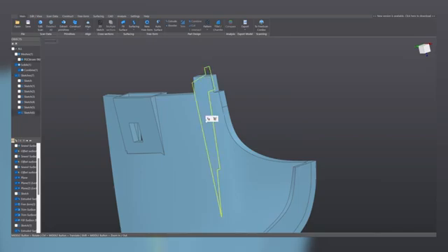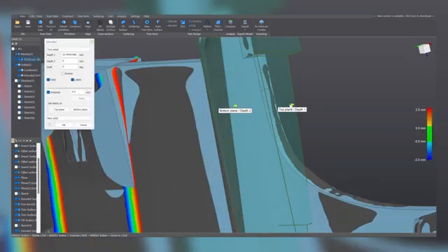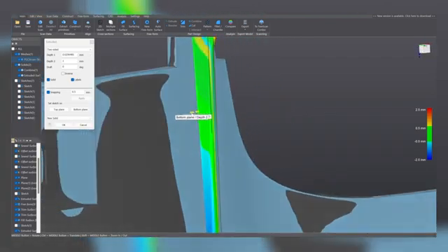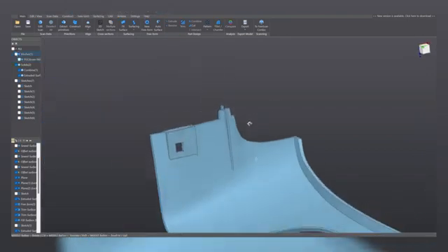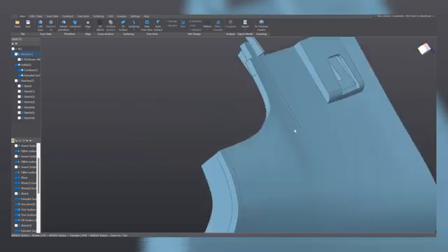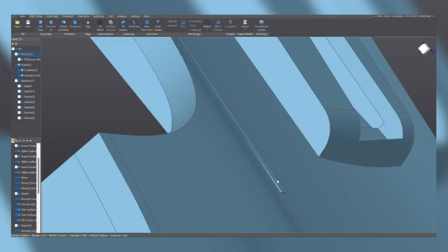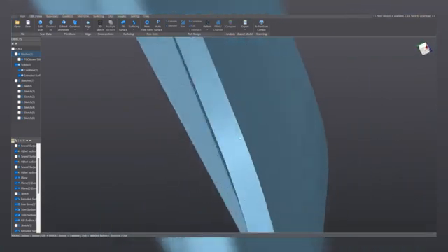Click on OK. Let's extrude it, let's display the mesh, and let's snap on these walls to define the extension of this extrusion. New solid is selected, click on OK. Let's hide the mesh, let's observe the result. Actually, I could correct my sketch a bit because the solid goes beyond, right?